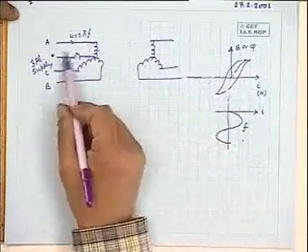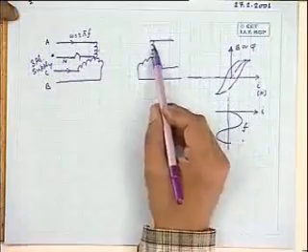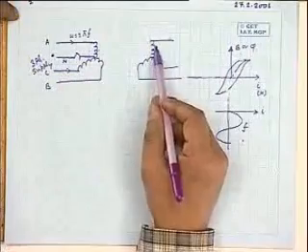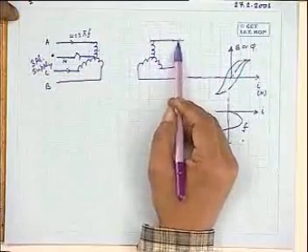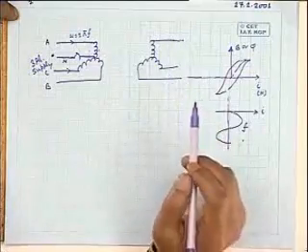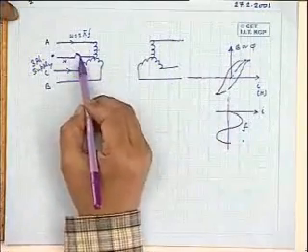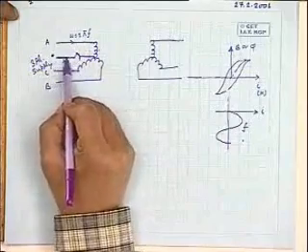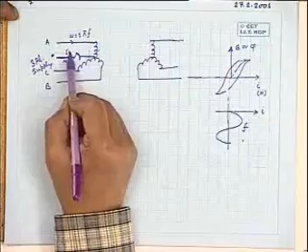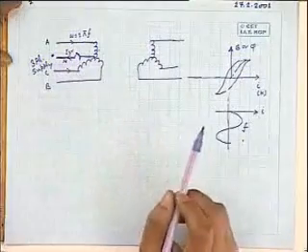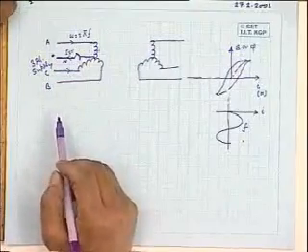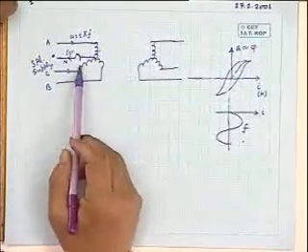Remember, in the earlier case, when this neutral was not connected, the phase voltage would have contained a third harmonic voltage, but line to line, the voltage would have been purely sinusoidal of fundamental frequency. But to avoid this problem in this fashion, this is one way of doing it, no doubt. The third harmonic current will flow via this neutral wire. But the frequency of this third harmonic current will be about 150 Hertz, is it not?